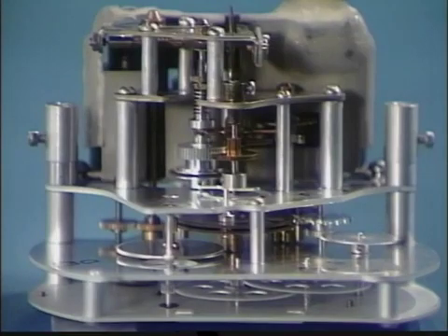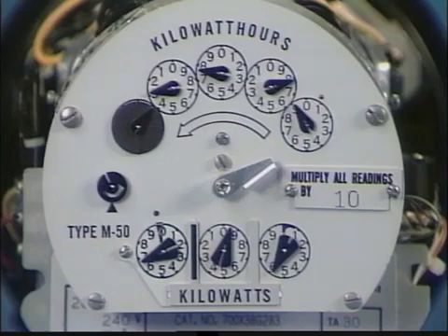The operation of a dial register is similar in principle to the operation of the sweep pointer register, but it's more complex in its gearing. The gear train drives 3 pointers rather than just one. The pusher arm is an internal mechanism, and it resets at the end of each interval, just as the pusher arm for the sweep pointer register.